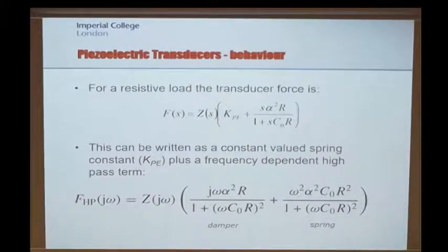So effectively, as we take our piezoelectric material and put a resistive load onto it, we're able to extract electrical power, because the force that the piezoelectric material now sees is a combination of a damping term, which is the thing that allows us to extract electrical power, but also we modify the spring, the stiffness of this device a little bit, and therefore we change the dynamics slightly. I think this is also something that Michael mentioned yesterday in his talk: you will change and shift the resonant frequency slightly as you start to load up these piezoelectric devices. And this is one way in which you can characterize that shift in resonant frequency.